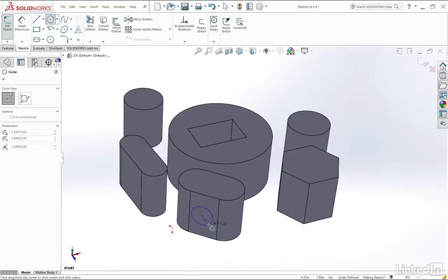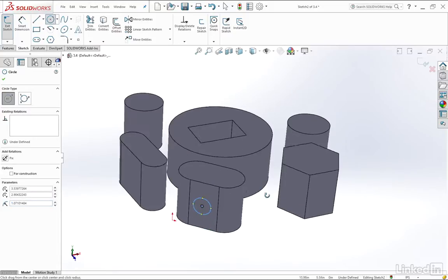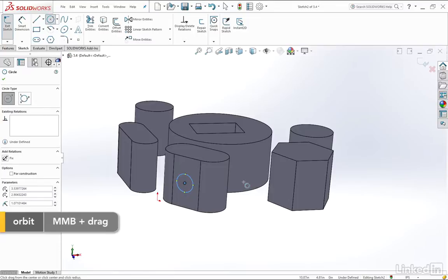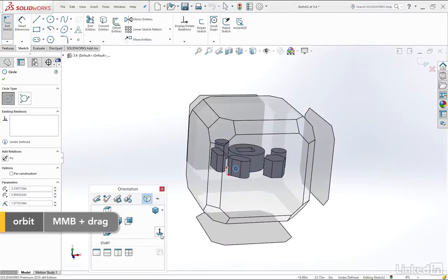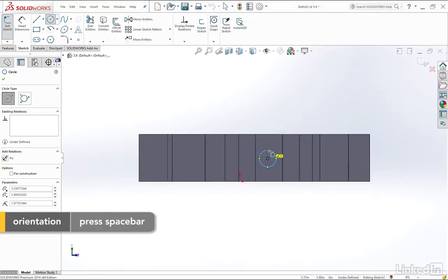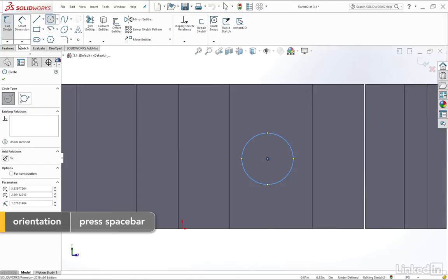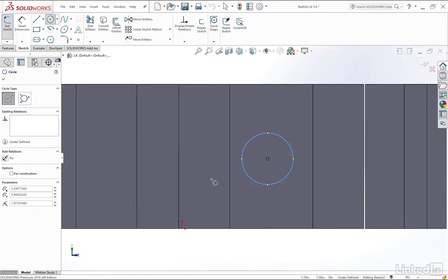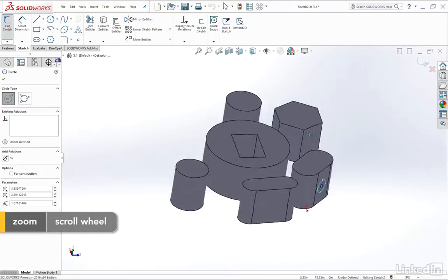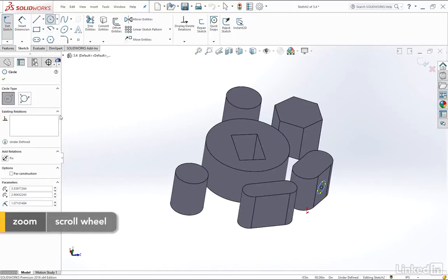I'm going to draw in 3D here, so I'm looking at the view in 3D. I'm not drawing in 3D. Or I can click on the space bar, and I can click on this one here called Normal To, which then will look directly at that shape. Once you have the shape, you can add dimensions if you want. You can tie it into the origin if you want. You can do a lot of things, but in this case, we're just learning about the Extruded Cut feature, so I'm just going to leave it as is.